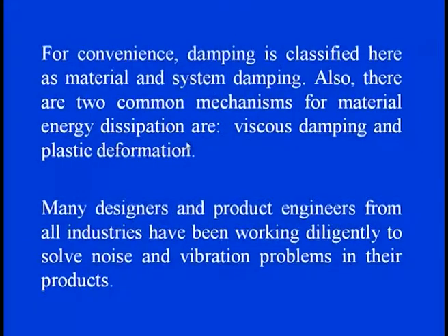And also there are two common mechanisms for material damping in which the energy dissipation takes place, that is the viscous damping, and the other is the plastic deformation. So, these are the two common mechanisms we are going to focus on, to show how material damping is actually actuated on the system.